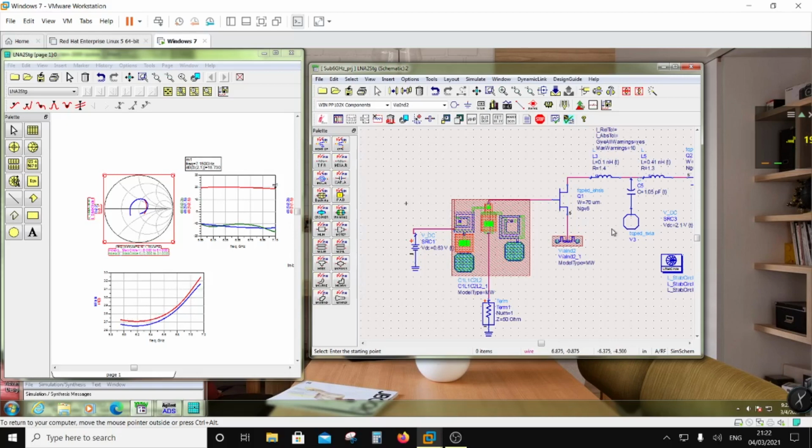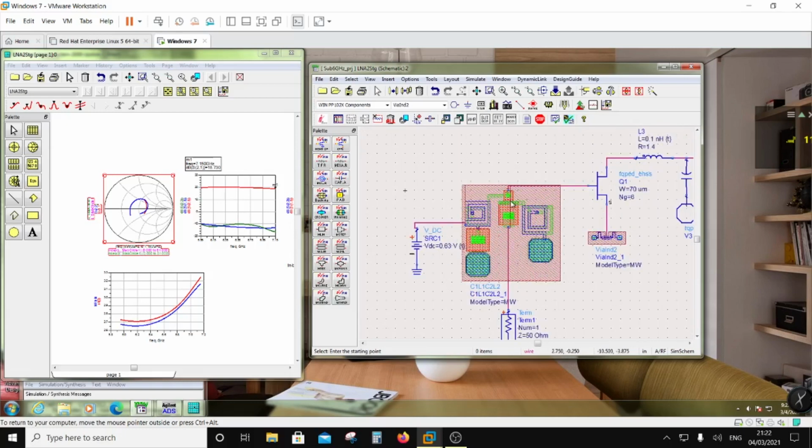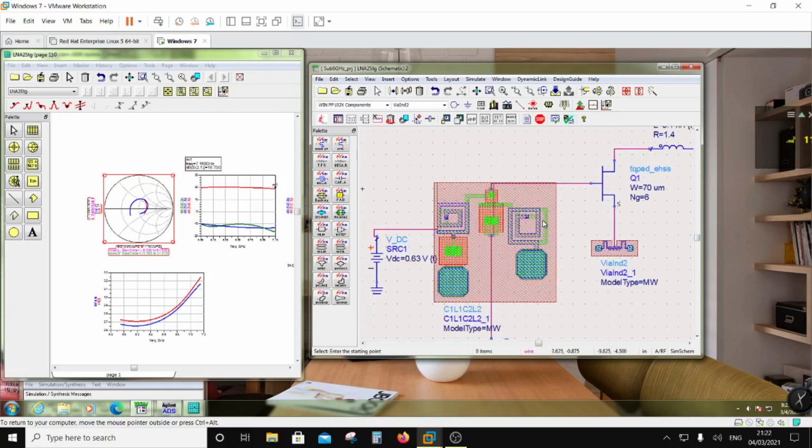So the scope of improvement is not anywhere else other than if you can minimize the loss of this input stage, right? And to minimize the loss of the input stage, you can reduce the loss in these inductors, because these capacitors, this path, RF path is so short. Then the loss is not because of these capacitors mostly. The loss is coming from the shunt inductors. So the only thing you can do here is make a wider trace on these inductors and try to get the noise figure to go down by reducing the loss.